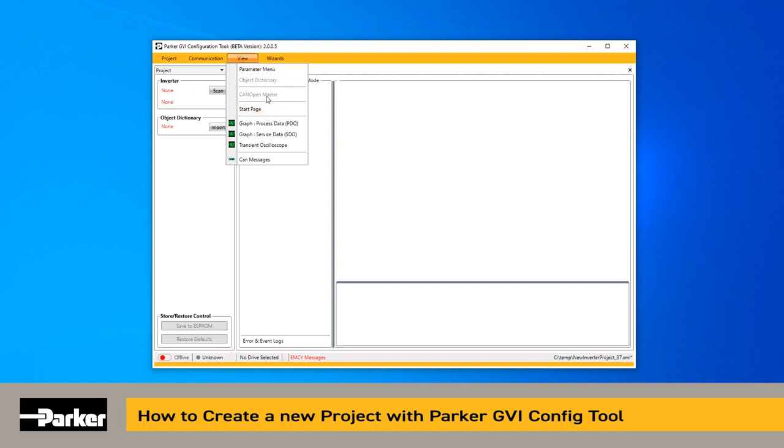We also have a CANopen Master simulation view. There's the start page, and we have three chart or scope views. We've got a chart view for the process data objects and one for the service data objects, and then we have this faster oscilloscope, which uses the firmware to capture data on a much more deterministic and fast basis. We also have a CAN messages view, which allows us to see the raw CAN messages going on the CAN bus.